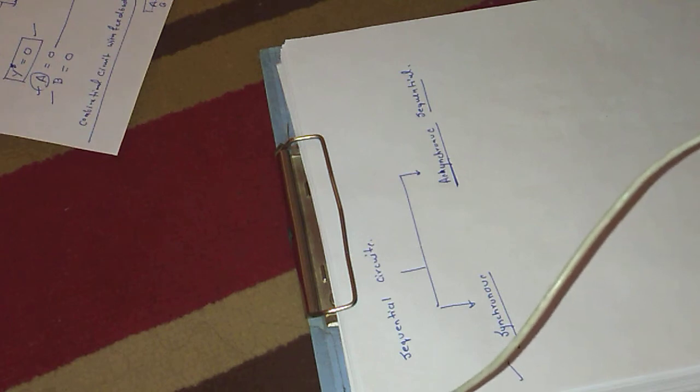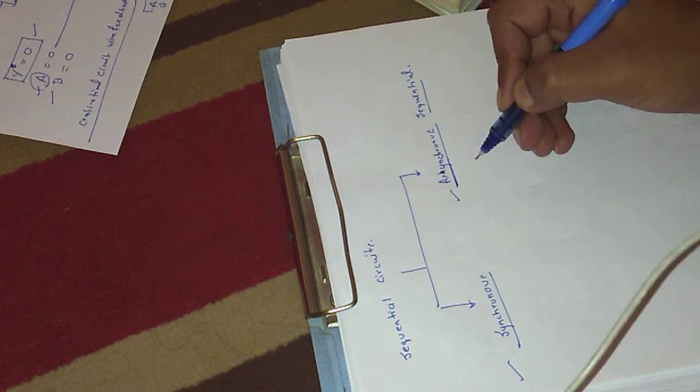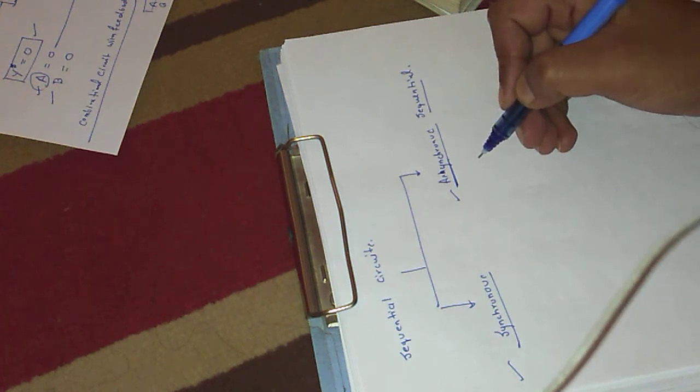In a synchronous circuit, the change in input signals can affect memory elements upon activation of clock signals. But in case of an asynchronous sequential circuit, memory elements are either unclocked flip-flops or time delay elements.